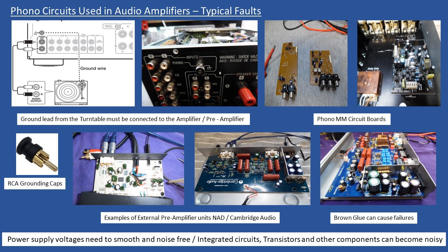And these components also can go thermally sensitive. So if you experience this, you can almost hear a crackling sound. It's literally like a crackling or rumbling sound, and it may just be on one channel of the preamplifier, but it could be on both. And then when you look at it, you can't see anything physical, but it's a process of elimination. And now remember, that kind of crackling sound and noise can also come from other components as well.